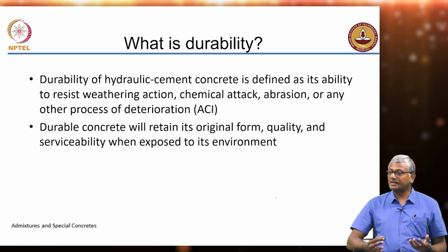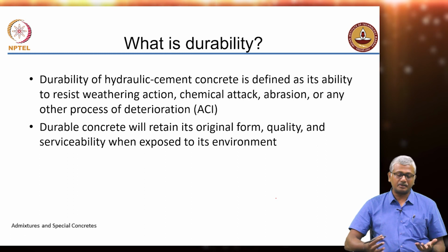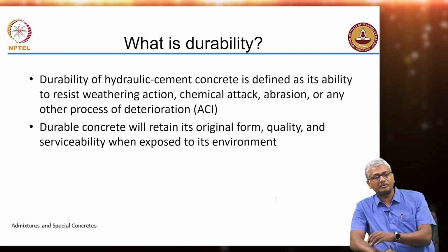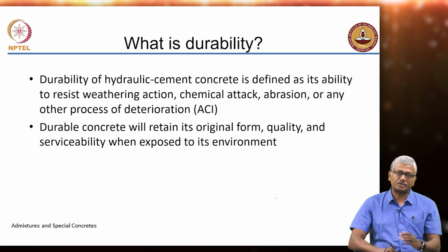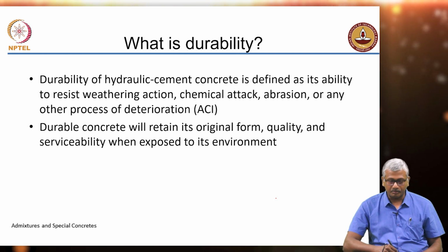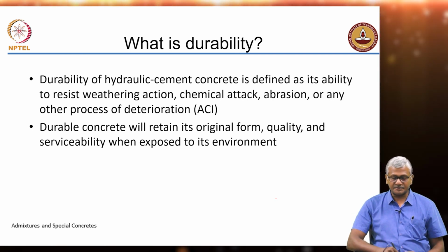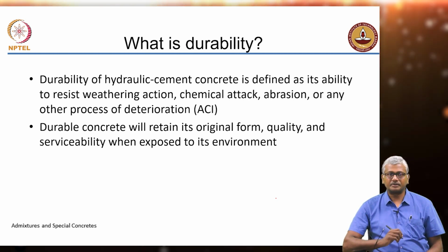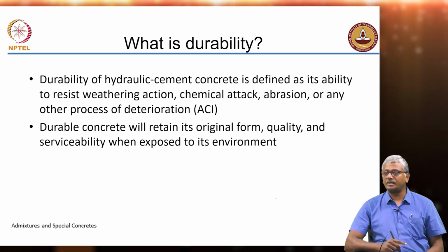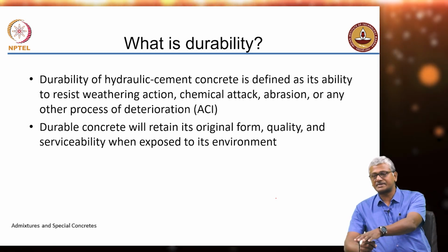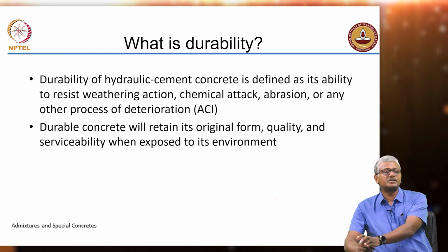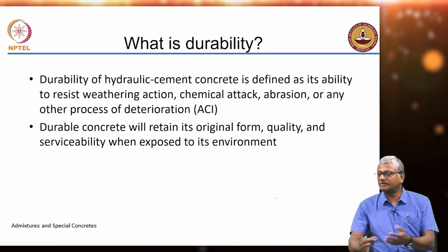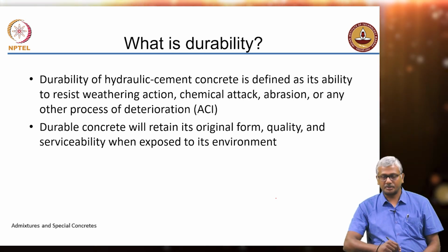So, durability is basically defined as the ability of concrete to withstand deterioration, okay, all kinds of deterioration. These are not load related, mostly they are environment related. That is the distinction between a structural loading related problem or a durability related problem. So, durable concrete is expected to retain its original form, quality and serviceability when exposed to the environment. So, we design for concrete durability based upon the environmental service. When we design in Chennai, the considerations will be different as compared to designing in Bangalore, right, because we have different mechanisms acting in different locations.